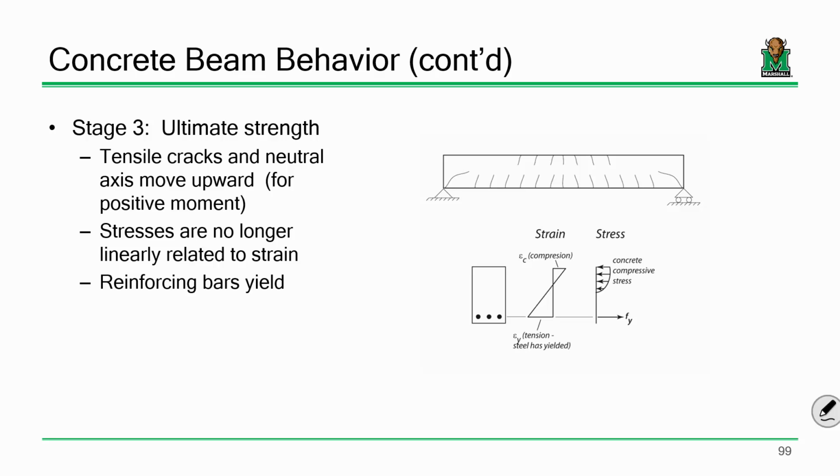We had about 1,400 psi in the concrete and about 18,000 or 19,000 psi in the steel, right? So it's still within elastic behavior. If you're talking about grade 60 bars, it's not going to yield until you get to 60,000 psi. And if it's 4 ksi concrete or 3 ksi concrete, we're still within relatively linear behavior.